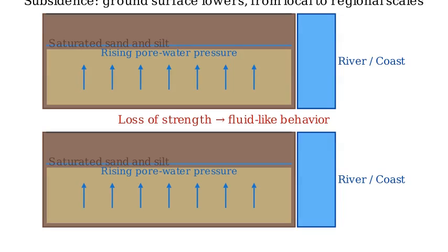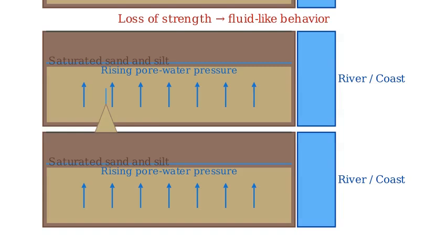At the surface, liquefaction leaves clear clues. Sand boils erupt as pressurized water carries sand upward. Cracks open, and the ground spreads laterally toward free faces like the river. This lateral spreading stretches the surface and drops blocks downward and outward.